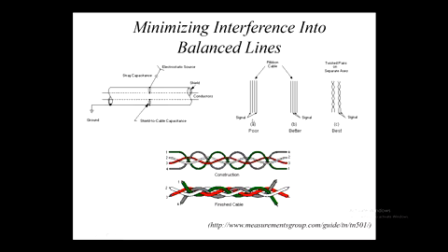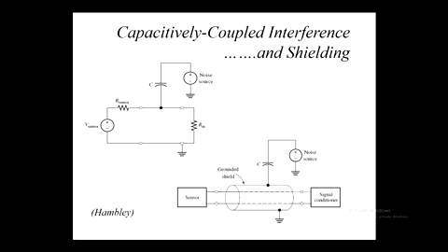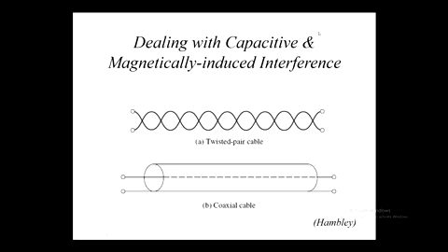Well, if it's a digital line, then we can use alternate earths between signal lines. That happens a fair bit. Notice here that the signal lines are constrained inside ground points. The other one is to use the twisted pair as well as the shield. So back here, typically these are combined: twisted pair inside a shield.